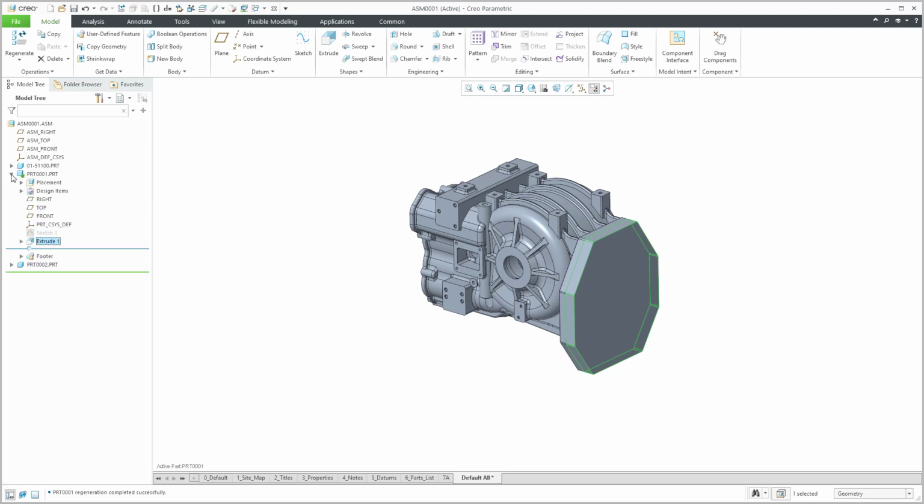So in this manner, I have created features in the part, and this isn't really top-down design in Creo Parametric. This is just designing with external references. And again, I used a bunch of techniques that are not recommended. So the way that you do things in SolidWorks, not really a great way of doing things in Creo Parametric.